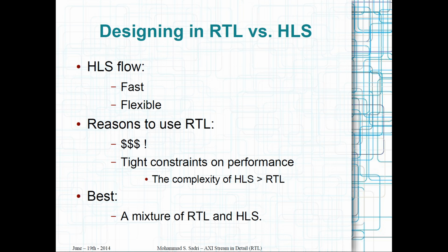So if you are trying to solve a problem and design a module, if it is something that you should have vision over every specific detail of the design, then maybe HLS is not a good option, because at the end the HLS will take your C code and will implement it in a way.